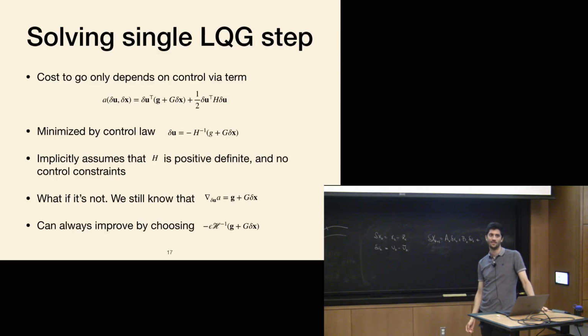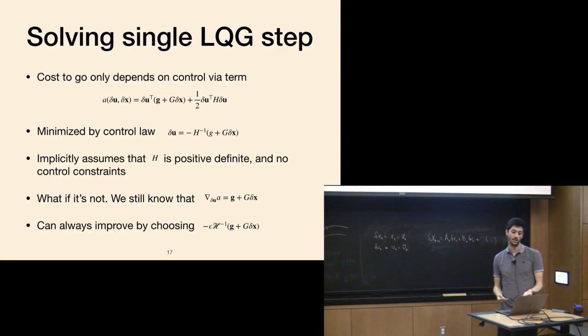Dynamics wouldn't be linear outside the linear range. Exactly. So you did a local linear approximation of your dynamics and you're solving the optimal control under that assumption. So that assumption is only valid locally. It doesn't make sense to take a huge step to somewhere else where that model might not be valid. So that's a really good point. And that'll be true in this case where we happen to know the dynamics but are doing a linear approximation to them. But it'll also be true in the unknown dynamics case. The same sort of insight holds.